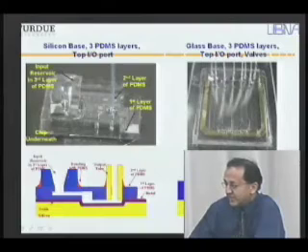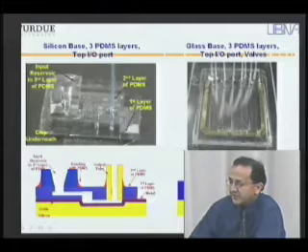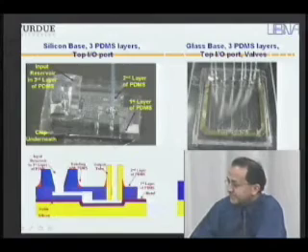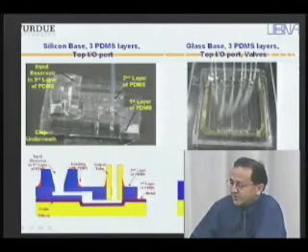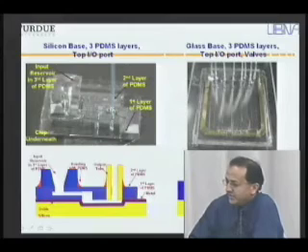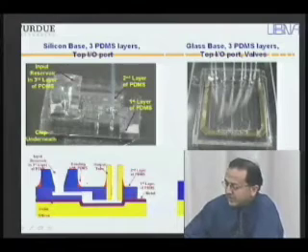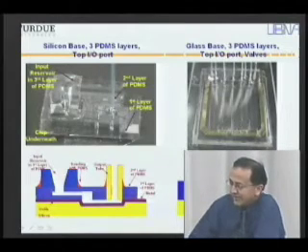Another example is a device here which is built on glass with some metal contacts. This device, originally the idea of air valves, the use of channels as air, was originally performed by Steve Quake. And the idea here is that if you can make these channels within the top layer, then when you pressurize these channels with air or fluid, these thin PDMS layers can bend and you can make valves. And once you make these valves, you can operate them sequentially to make a pump, for example.